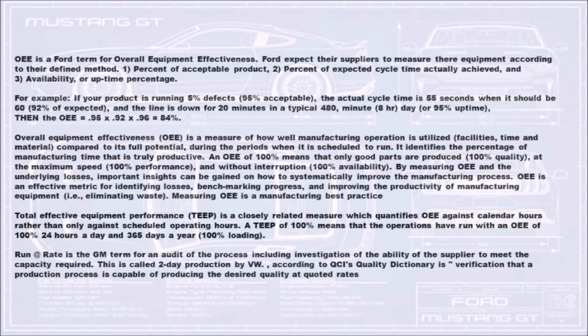More or less. OEE is a Ford term for overall equipment effectiveness. Ford expects their suppliers to measure their equipment according to their defined method: 1. Percentage of acceptable product, 2. Percentage of expected cycle time actually achieved, and 3. Availability, or uptime percentage.